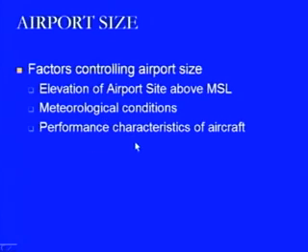Similarly, the performance characteristics of the aircraft will also have an effect, because of the speed of the aircraft at which it is landing. If the speed is very high, then it requires a bigger runway strip, and therefore the size of the airport will increase. But smaller aircraft require shorter runway strips and smaller facilities, so obviously the size of the airport will be lower.